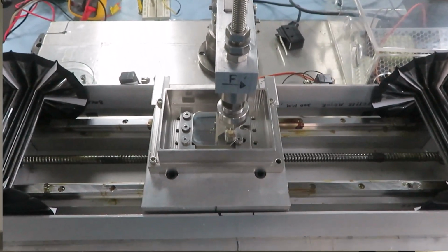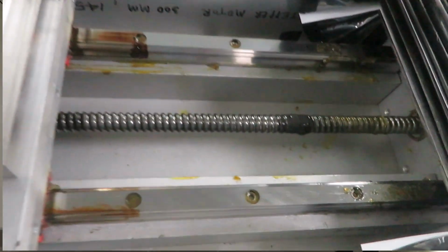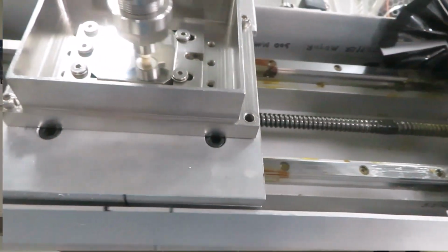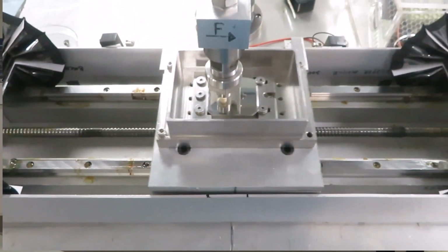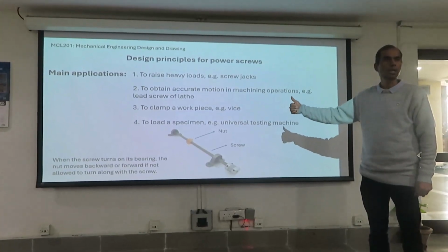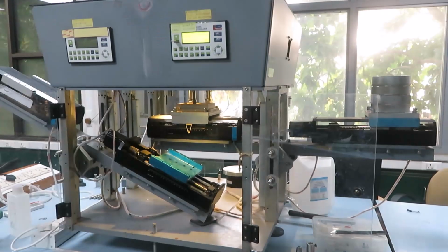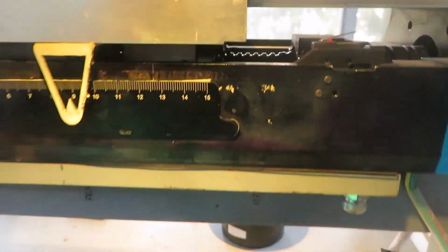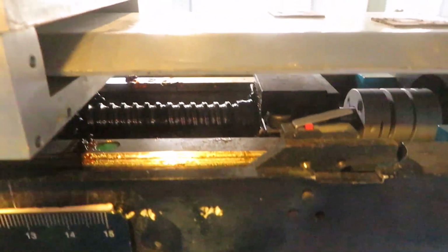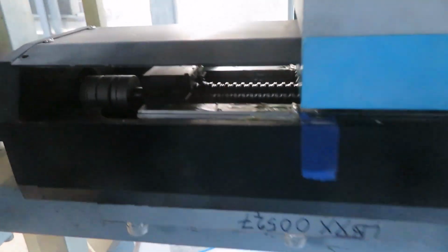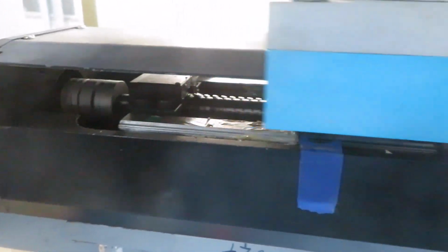Okay. So for example, if you have power source on this right side and you turn the screw and you restrict the rotation of the nut so that nut doesn't rotate with the screw, then in that case it will apply some force on the nut and nut will move up or down. Okay. So that's a very, very simple mechanism, okay, but very, very important, because there are a lot of machines which has got this power screw. Okay. So you can see a lot of such equipments.